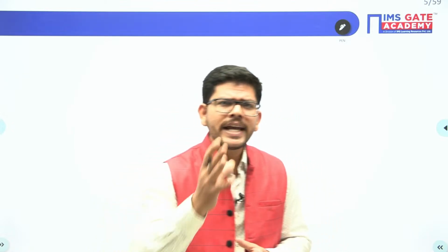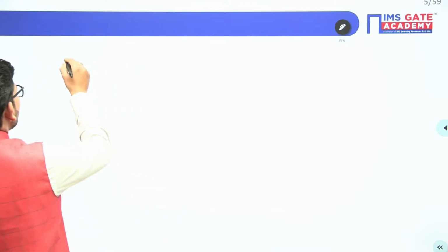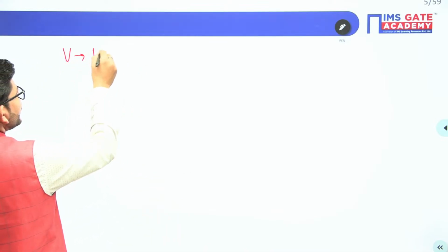Now when you are about to realize a switch, you have to remember one important fact. When you are realizing a switch, the one thing you have to remember is that a switch may be realized based upon the voltage that it will block during its off state, mind it, the voltage that it blocks during its off state, and the current that it will conduct during its on state. So these are the 2 important facts that you should remember. The voltage blocked during off state.